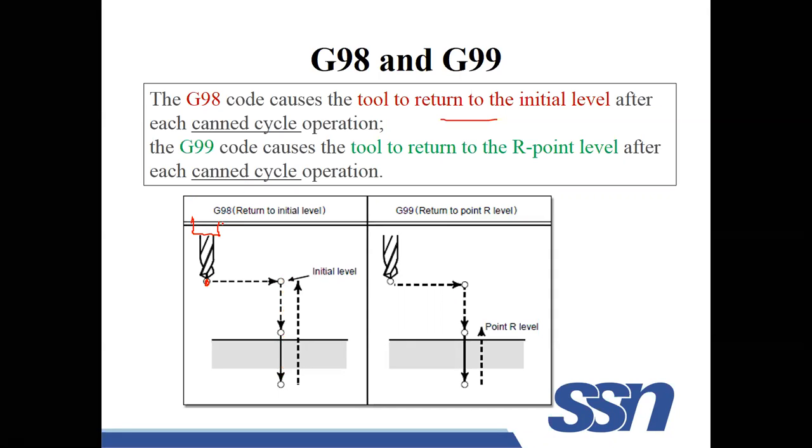For flat surfaces, people are referring to this. See, I have a job like this. Assume this is a horizontal line. I want to make a hole here and here and here. I can keep my tool reference point 1 mm away from the surface. It is a very small value. So every time I can move and perform the operation. Suppose my job has a step, like this. In this case, the reference will be different.